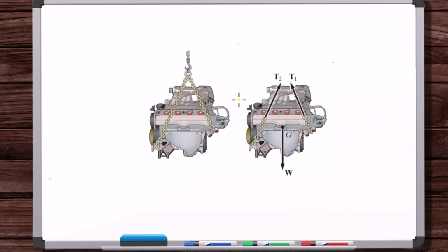Okay, now if you look closely at this free body diagram, this looks to be a planar free body diagram, but I imagine the chain is wrapped all the way around and then loops back up here on both sides, so it's symmetrical. But you've got 4 total chain forces, 2 in the front, 2 in the back. If you look closely here, it looks like they've made an imaginary slice in the chains and then applied forces to the chains at those imaginary slices. That's something that you can do to make a free body diagram.